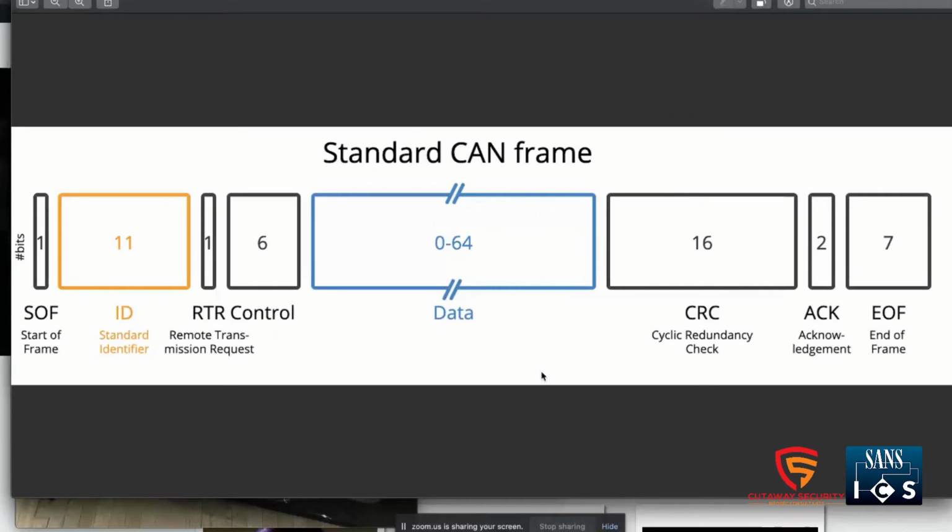If the transmitter, so if I'm sending the message, doesn't detect the low, a logic 0 on the line at that point, then I know that either no one heard my message or they heard it and they thought that something was wrong with it. So that's another way to build some kind of reliability into the system.